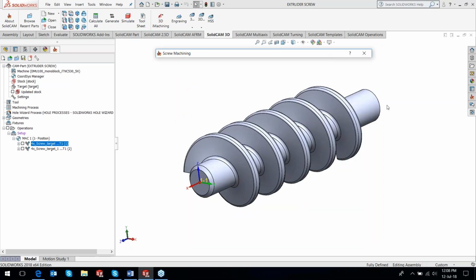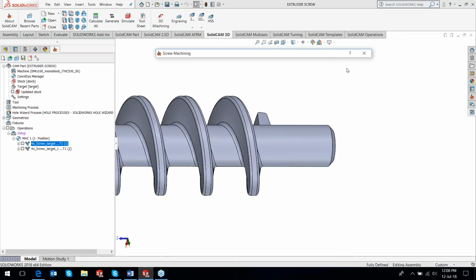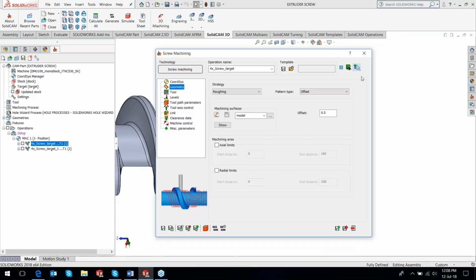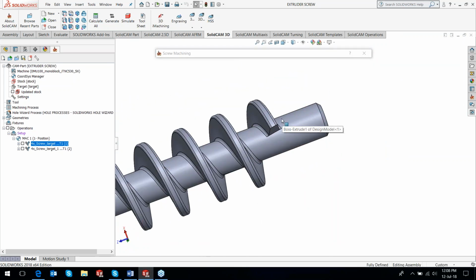For example, let's look at an area here. Let me switch off this tool at the moment. We have got quite a lot of space that's there after the fin is finished. So even in this area, if I select the offset option, it will just keep offsetting the profile that it gets. But if I use the second option, which is offset and spiral, the offset will stop exactly at this point. No more further offsets will be created.